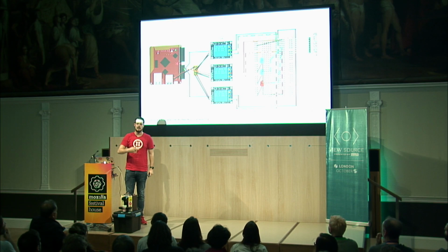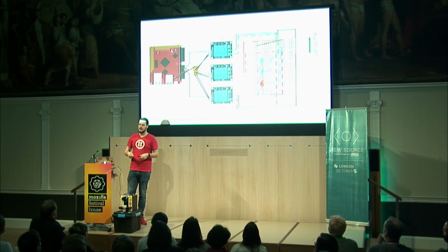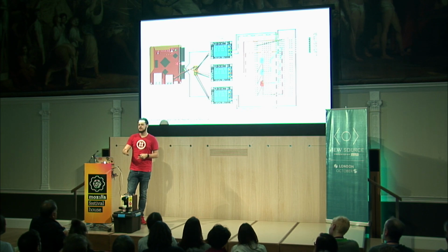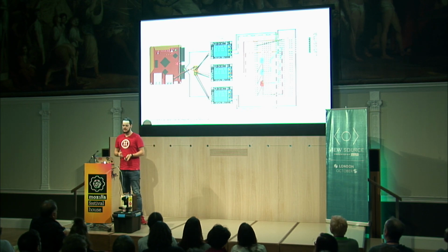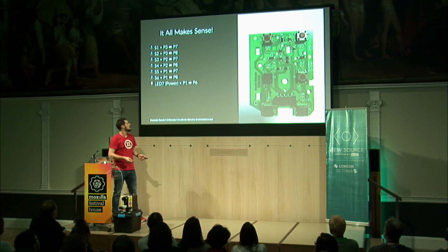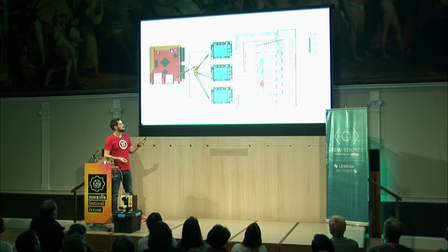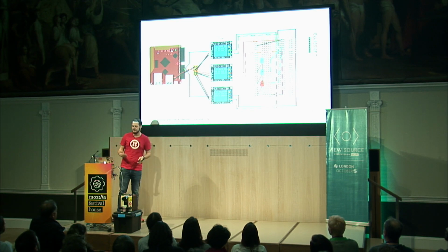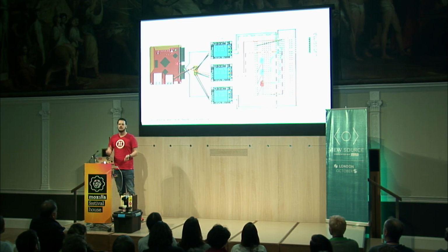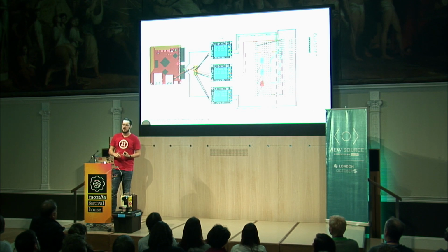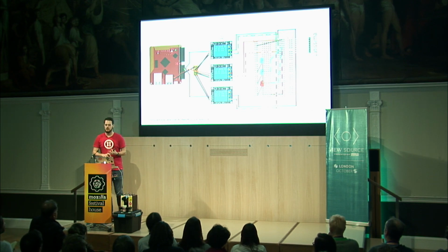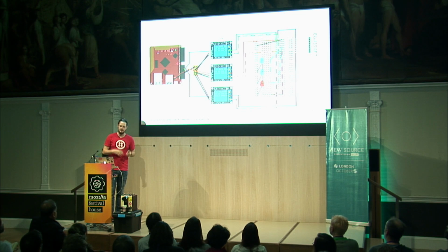Like you can turn it on and off, and you can just put wires into it, and then depending on what value you set, you can either open the circuit or close the circuit. So what we did is we wired up the same thing we have here, just that we used the relays for it. And we only had 4 relays, so we used 3 of them for the core functionality, which was on-off, espresso, or a normal coffee. And we mimicked the switches with that.